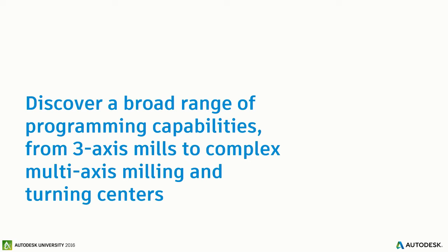Alright, so as we've seen, FeatureCAM utilizes feature-based programming. Because feature-based programming uses a set of customizable parameters, the same concept can be applied to turning and turn mill parts. FeatureCAM has the ability to recognize features from surfaces and solids in turn and turn mill just as it does in milling. This allows you to program your parts the same way every time, with the same expected results, since you will be using the same smart settings every time you program.